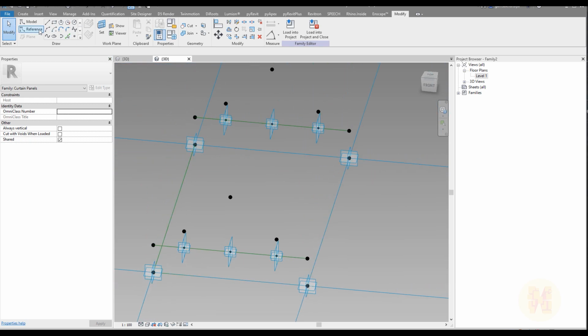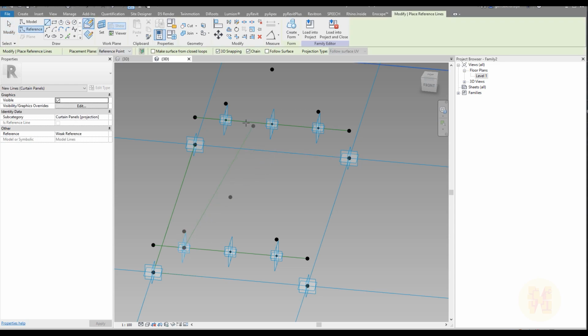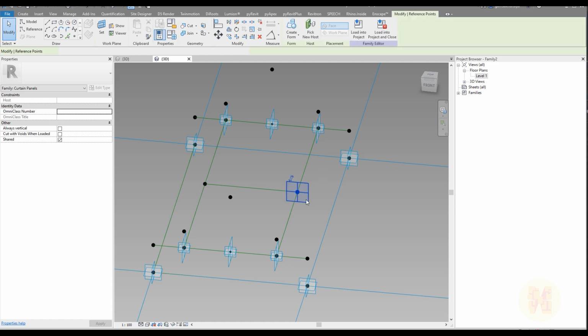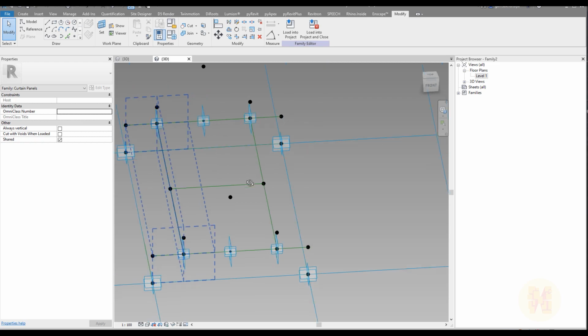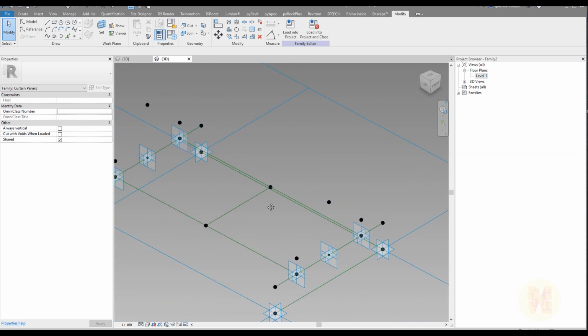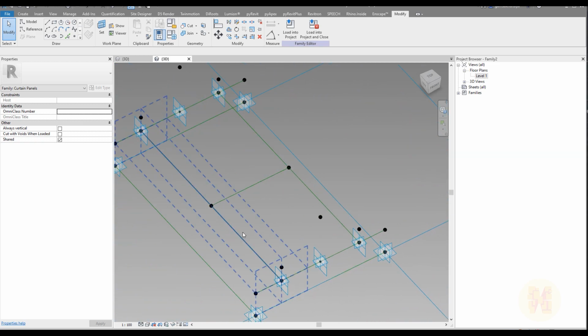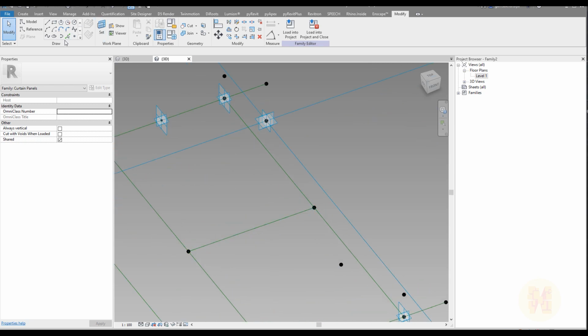How can we do that? Again, to the reference one, and let's create it here, this line and this line. Also, let's try to create it from the same direction so it will not mistake you. Let's create from this point to this, because we need the middle point. As you can see, if I select this point, it's exactly on the 0.5. Whenever you change the size, it always will be on the 0.5. So we did it. We need 2 extra points, actually 3 extra points.